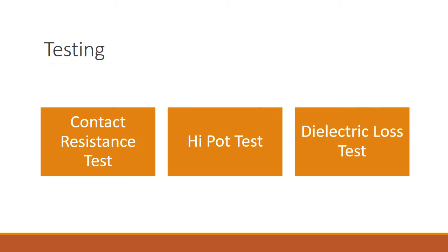One of the most effective testing methods for predictive and preventive maintenance is this power factor testing. Without performing an inside visual check, power factor testing may also be used to uncover equipment insulation issues, and as a result, maintenance costs and downtime are significantly reduced with the use of power factor testing.